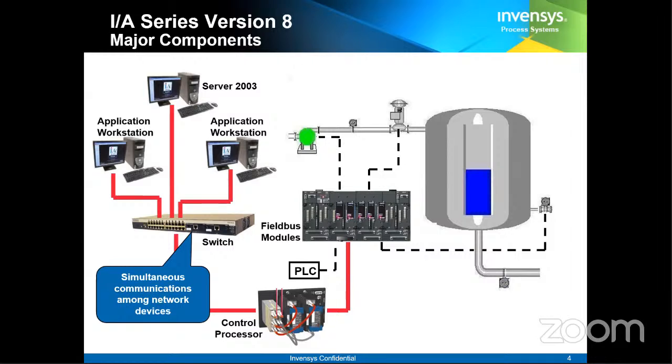In this case, let us say the primary controller fails and the secondary has taken over. What is our next target? We need to replace that controller. In the case of the Foxboro DCS system, it is simply plug and play. You can remove the primary controller, bring a new controller from the spare stock, and simply plug it in. The neighboring controller will share all the data with the new controller, and again they will start working together.